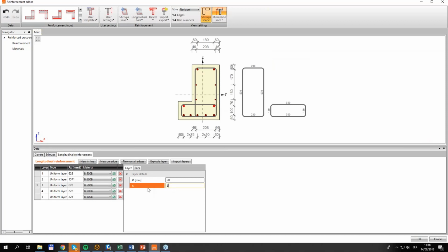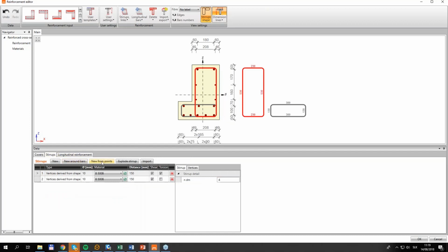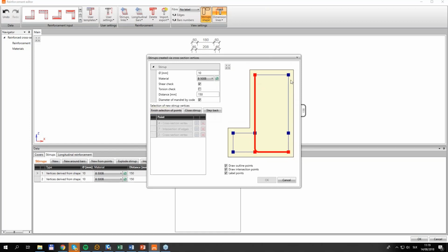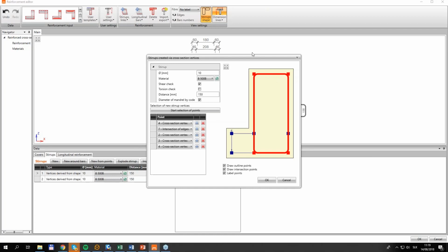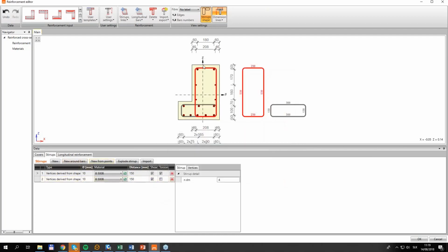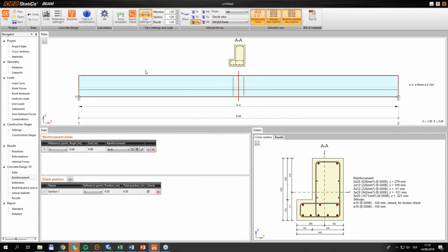And for instance, I want to include 3 of these here. So you can see that it actually generated the reinforcement, which I would do if I wanted, let's say, new from points, and it has already been defined on the cover, right? So you can see other webinars or our tutorials on how to work with that. Yeah, okay, so let's see. When I click OK, you can see the reinforcement here. It applies to the whole zone.